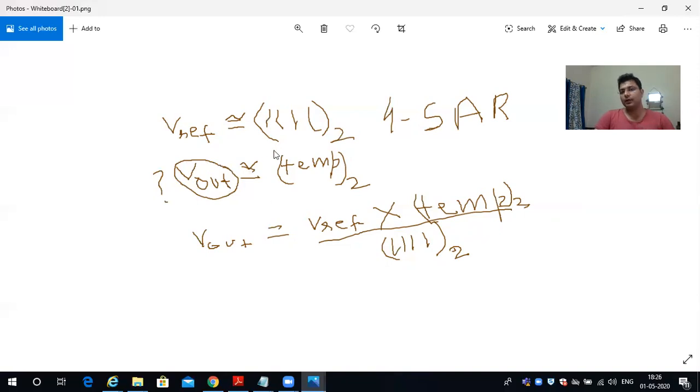That would be approximate to whatever we will get out of the conversion in 12 bits or 4 bits. This is 4-bit approximation. So whatever we have received out of conversion after passing it through ADC module, that is what we received in the data register.